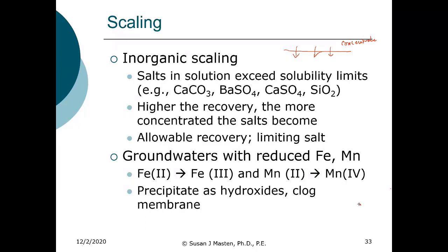And then we can have a concentration gradient develop on that membrane surface. That results in higher concentrations of more insoluble materials, and then they deposit on the surface. So you get these precipitates, and that results in scaling.